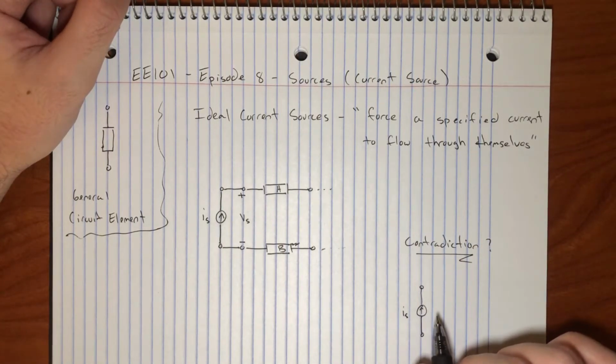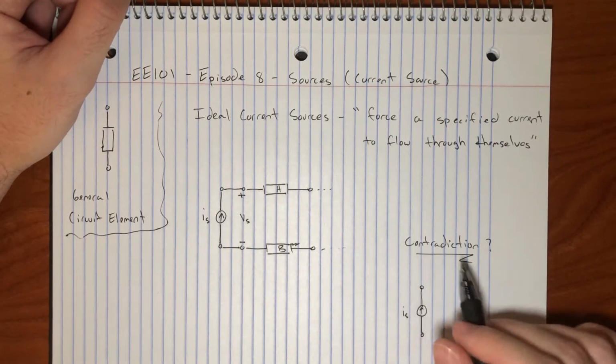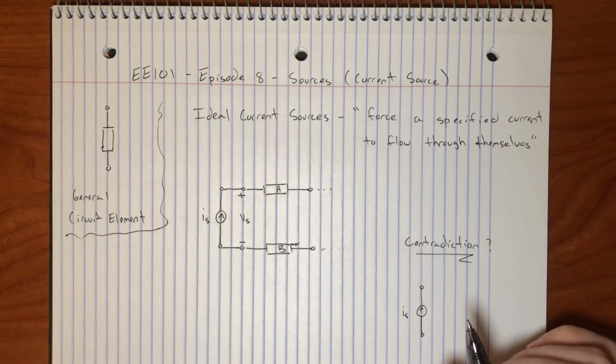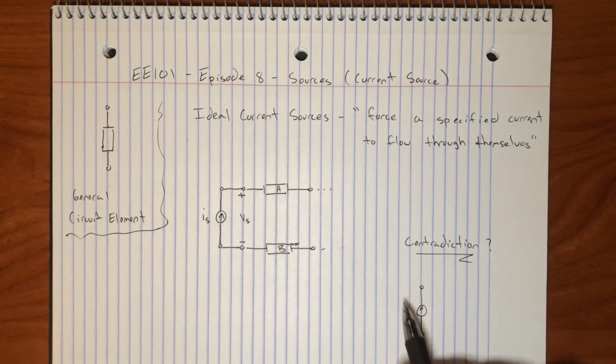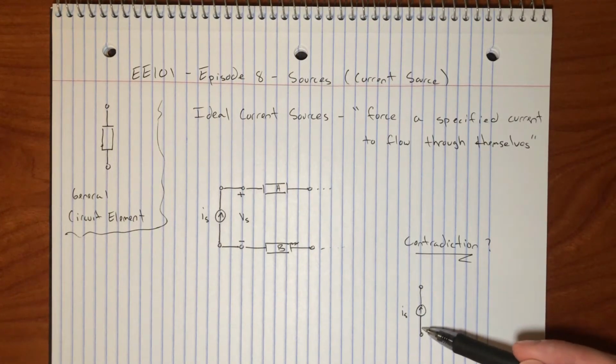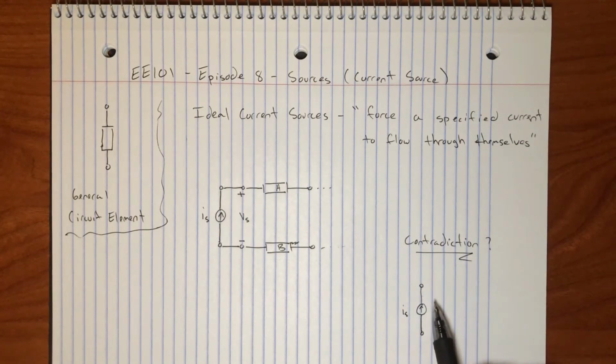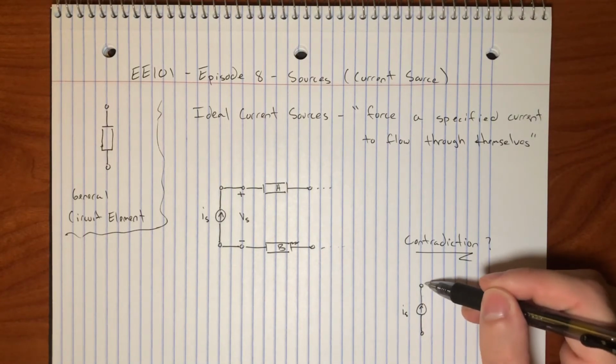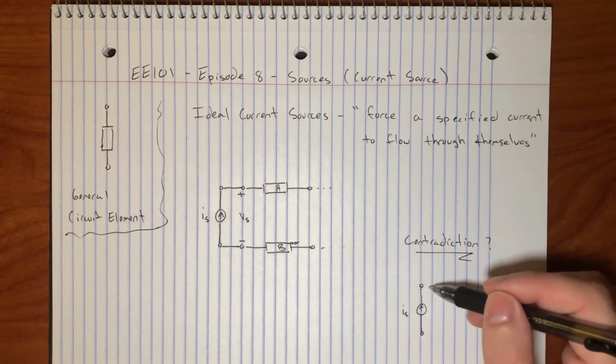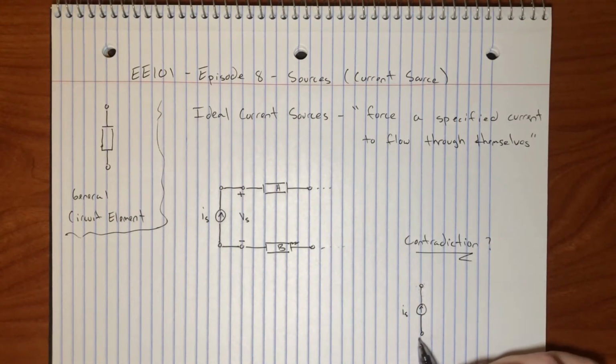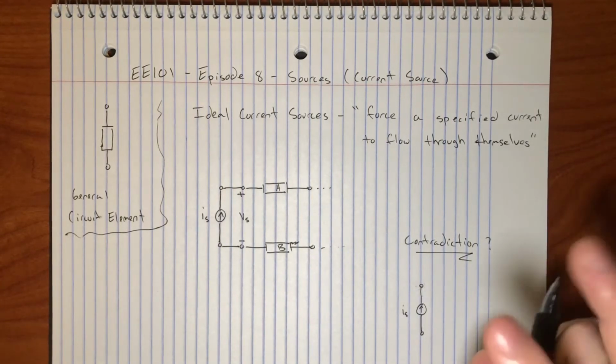And it's interesting because, well, what about the case when there's nothing connected to it? So if you remember from the previous video, I talked about the concept of an open circuit. And so this node right here, you can actually say, and this is the most trivial case, that there's a node on either side of this circuit element. The only problem is only one circuit element is connected to either of these nodes. And so one circuit element on its own is not a circuit. There's no loop here. There's no path for current to flow. And each of these nodes doesn't see any other element. There's nowhere for current to go in this direction, and there's nowhere for current to come from, to enter. So either side of this ideal current source is an open circuit.